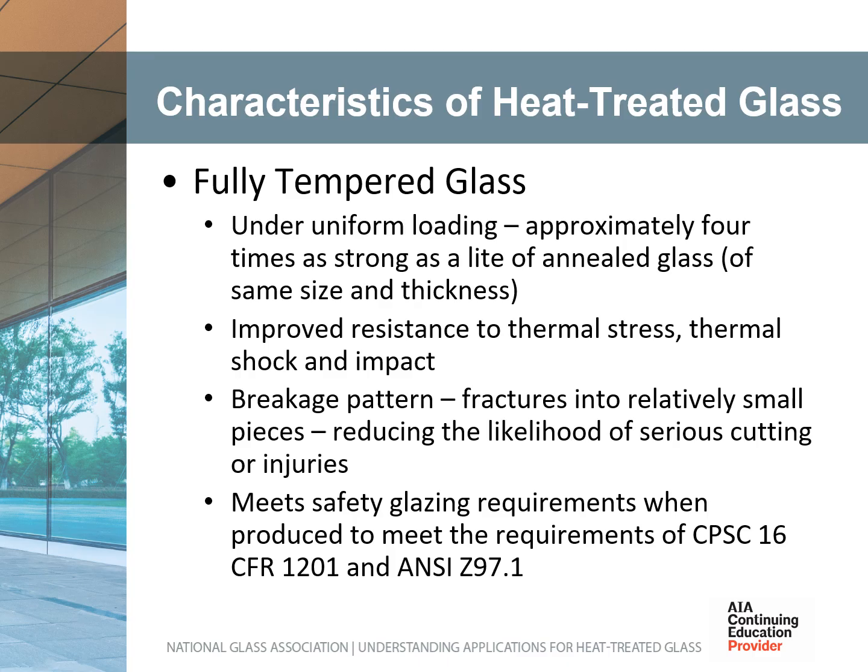When broken by impact, fully tempered glass immediately shatters into relatively small pieces, thereby greatly reducing the likelihood of serious cutting or piercing injuries in comparison with ordinary annealed glass. To qualify as a safety glazing material as defined by ANSI Z97.1 and CPSC 16 CFR 1201, the 10 largest particles taken from a broken fully tempered light of glass weigh no more than the equivalent weight of 10 square inches of the original specimen when tested according to the standards.